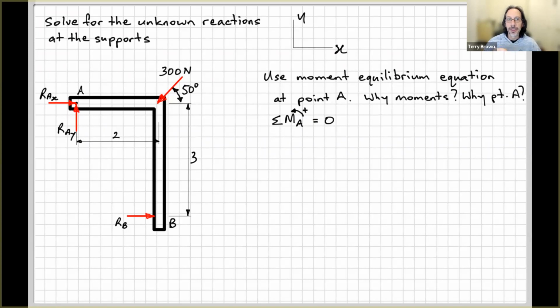Then, strictly speaking, the positive direction for a moment is anti-clockwise. Okay. If you don't know why, we might talk about that in another video, or go back and have a look at your calculation of moments using the vector equation. Now we want to work out our moments.